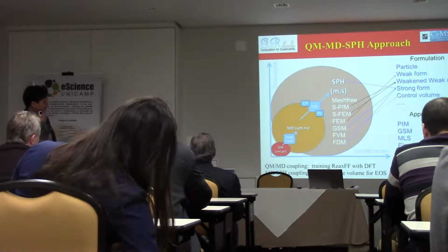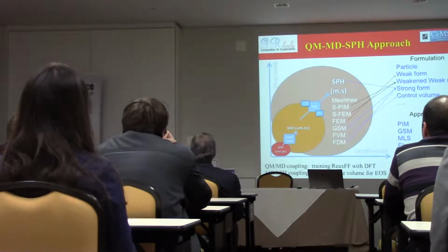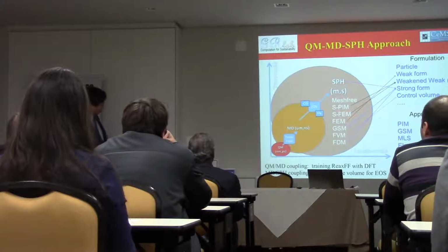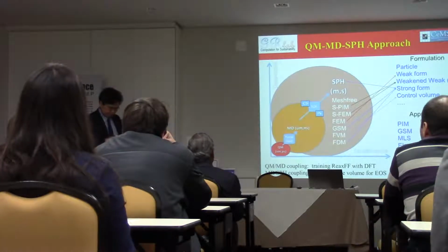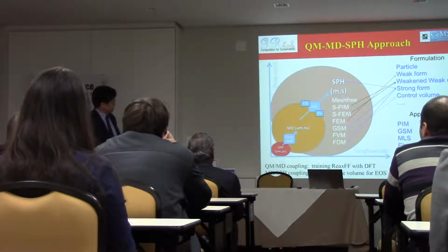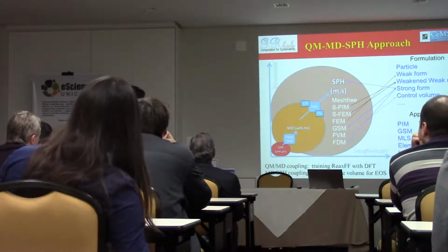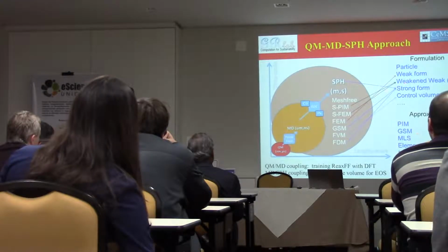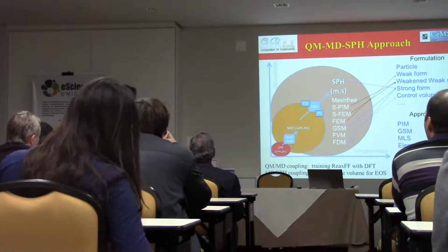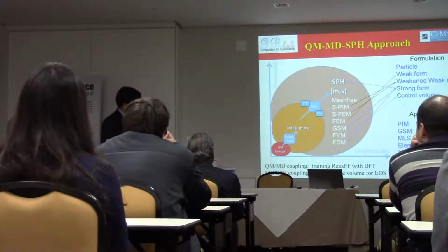So therefore, we moved on to study the so-called mesh-free technique. We came up with a technique that we call the smoothed point interpolation method. That method is a little bit different from the formulation of the finite element method. In theory, it uses the so-called weak formulation. We call it W2 formulation. And those techniques were further